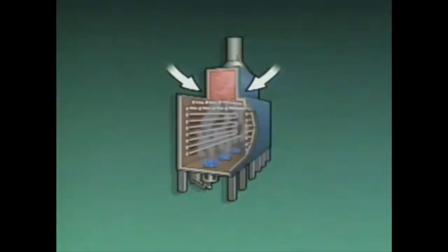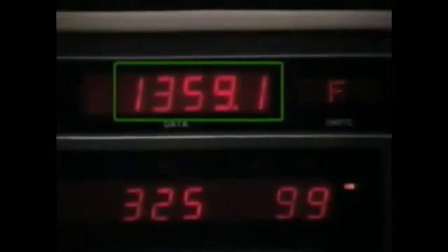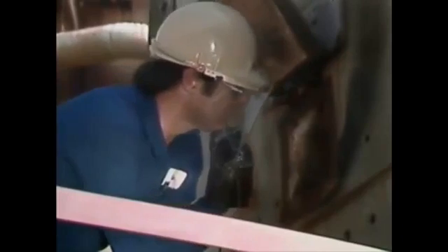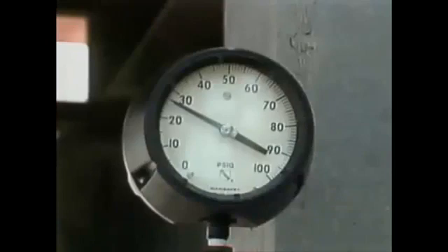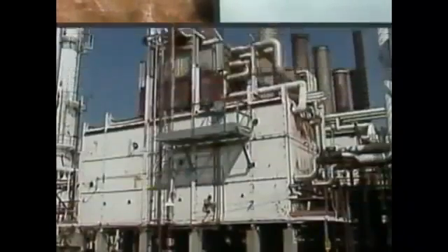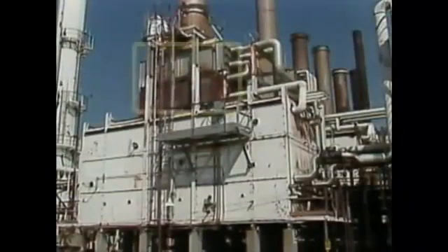With afterburning, you may see smoke coming from the stack, as well as excessively high stack or convection section temperatures. And since afterburning is caused partly by insufficient air at the burners, you may notice an overly hazy appearance in the furnace. To deal with this problem, you may need to reduce fuel pressure until the hazy firebox clears. Then you can use the stack damper and the burner registers to start adding more air to the burners. In addition, if the afterburning is a result of an air leak in the convection section, the leak should be sealed up and the furnace repaired if necessary.